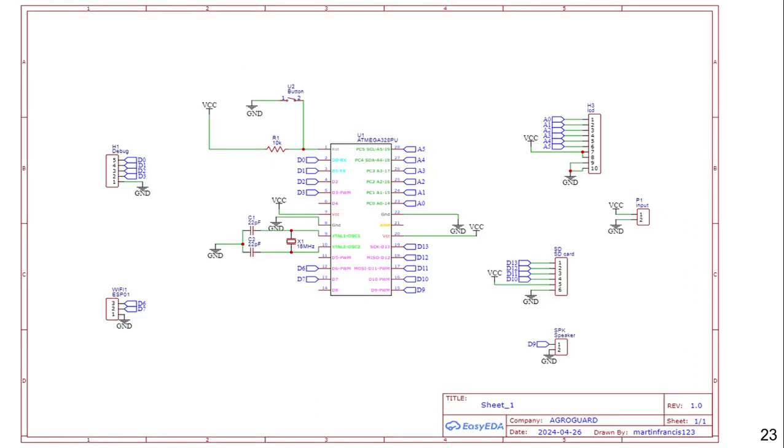The circuit has been designed using EasyEDA. So basically we have a button here. This is for resetting our Atmega 328P when needed. In the H1 header we have debug pins here because we all know that Atmega 328P is a DIP IC. Sometimes taking it out and putting it on an Arduino to program it can cause damage to the IC. As a result, we have made debug pins in such a way that we can program it and debug at the same time, using the 2, 3, and 4, 5 pins.